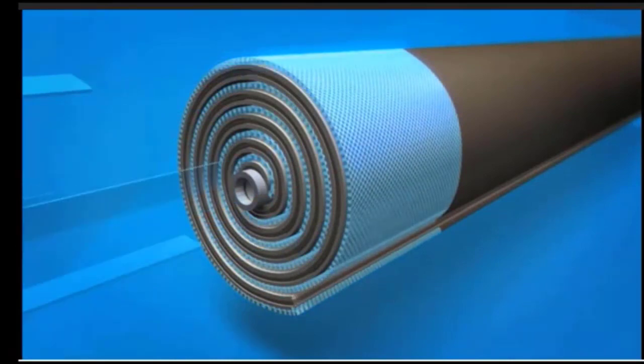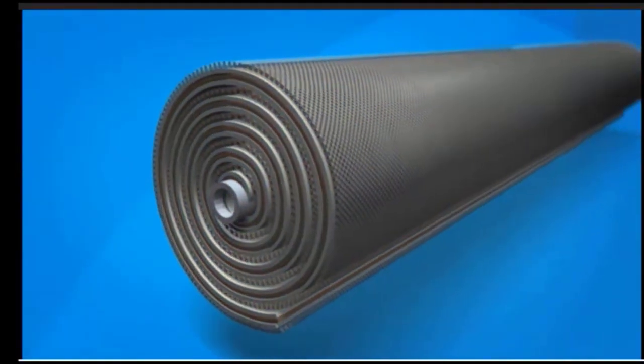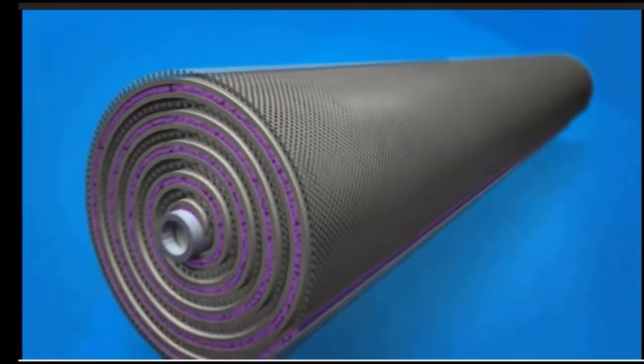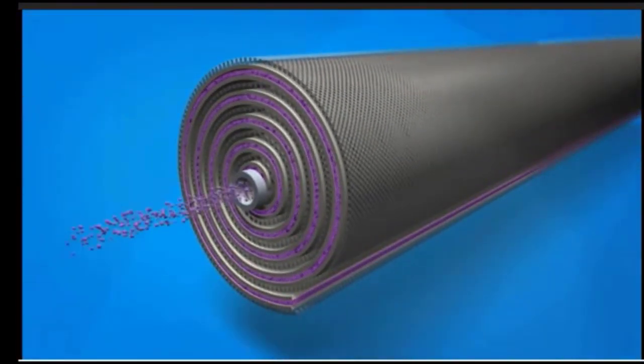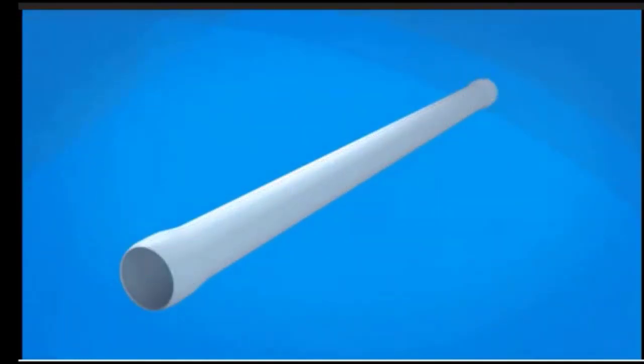Feed water is forced through the feed channel spacer and into the barrier layer of the membrane. Water passes through the membrane surface into the permeate channel. It flows in a spiral direction and collects in the core tube. This water is the final recycled water product, or permeate. There are 7 spiral wound elements loaded in one pressure vessel. Once the end adapter is connected to the last element and the pressure vessel is sealed, feed water can be introduced.